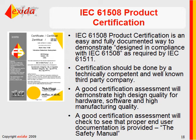61508 is a relatively complex standard, and a clean, fully documented way to demonstrate design compliance is to purchase a product that has been certified per IEC 61508. Certification really must be done by a technically competent and well-known third party. I have absolutely seen self-certifications done by manufacturers. These exist on the market, and there's nothing in 61508 that says people can't do that.